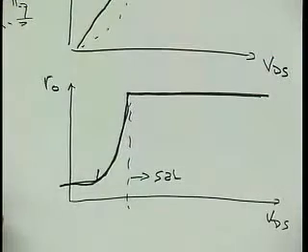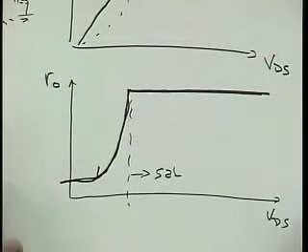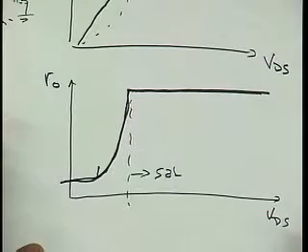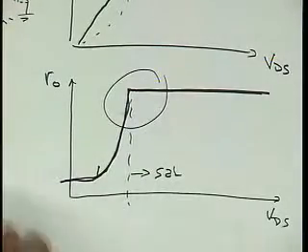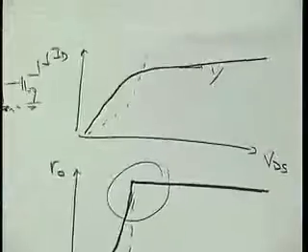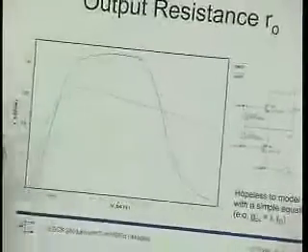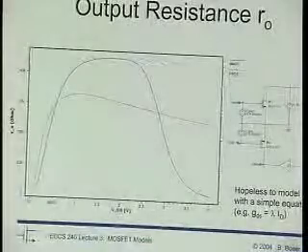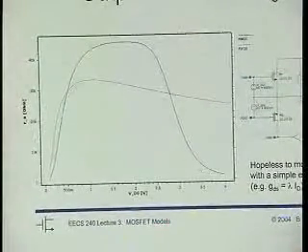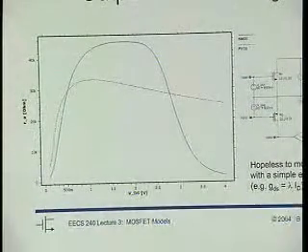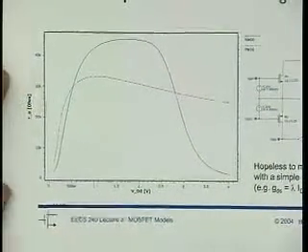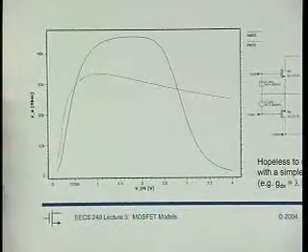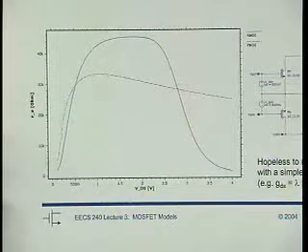Okay, so that's probably not what's happening in the device, right? So lacking a real device here, I ran SPICE and evaluated R-out for various VDS for both NMOS and PMOS, and well, it looks remotely